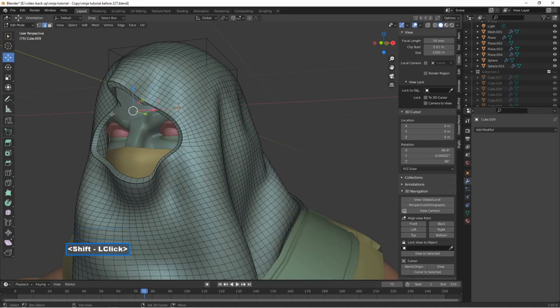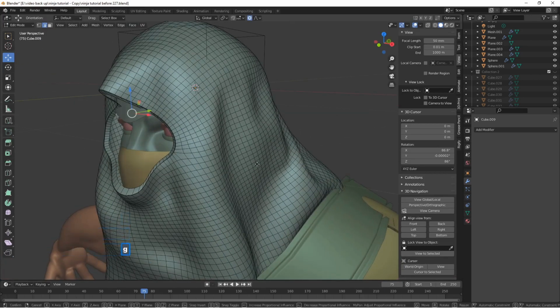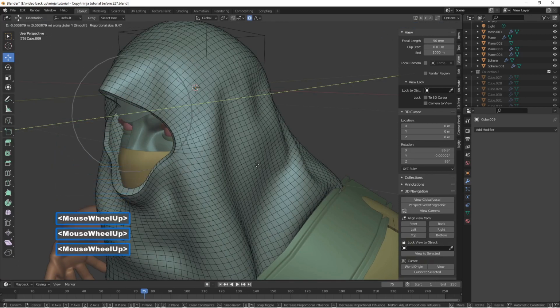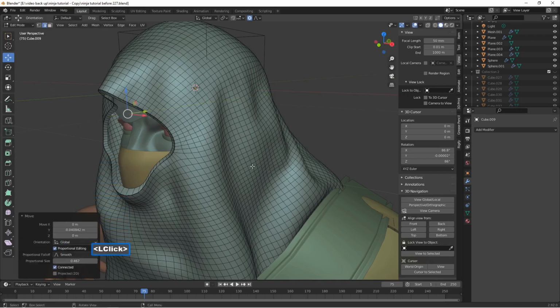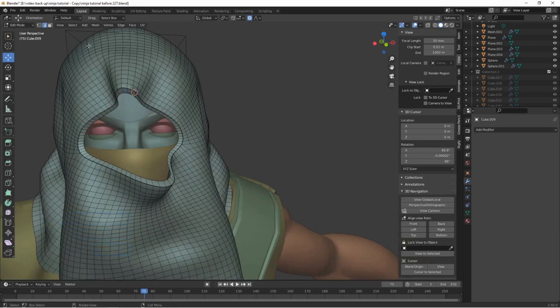Same thing here. So I'm selecting near here. I'm going to press O to turn on the proportional editing. I'm going to press G and then Y. Shrink my area of influence to have that not intersect. I also want more of the face to show. So I'm going to press C. When I say face, I guess I mean more of the Ninja Master show.